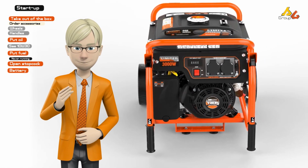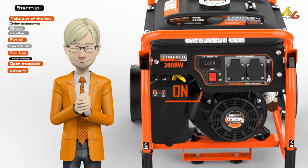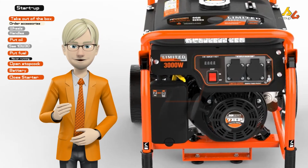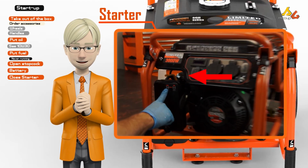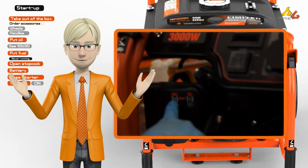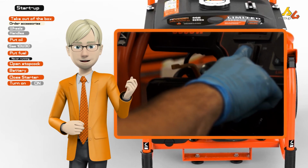Immediately before starting, we will close the air inlet from the starter lever. This will produce a richer fuel mixture and will facilitate the initial start. Once closed, we will start it with a manual puller or with the switch or ignition key if it's electric. After a few seconds, we will take the starter lever to the initial position, letting it breathe, and we will make sure that after a few seconds the engine is stabilised and the generator will be ready to work.